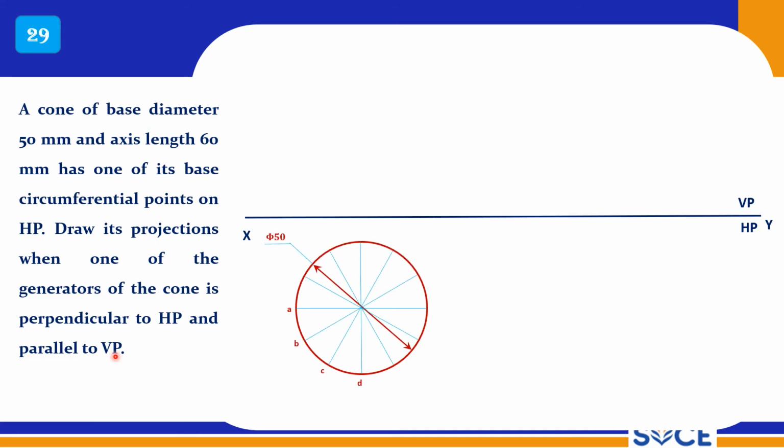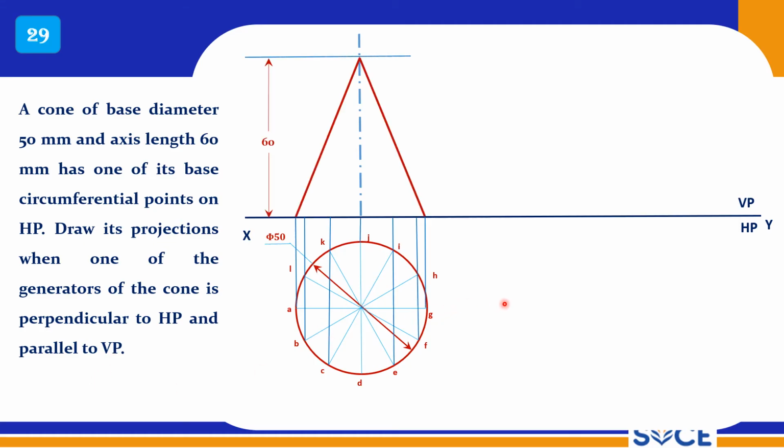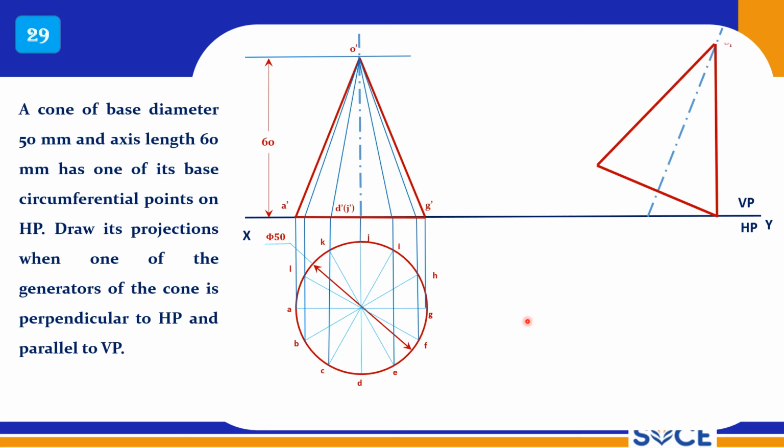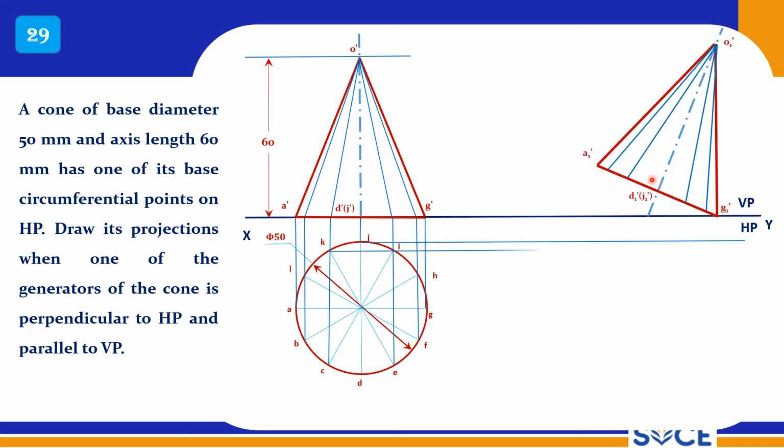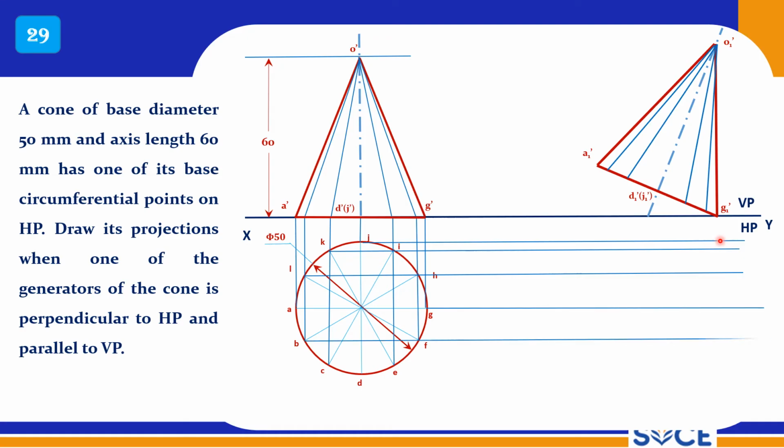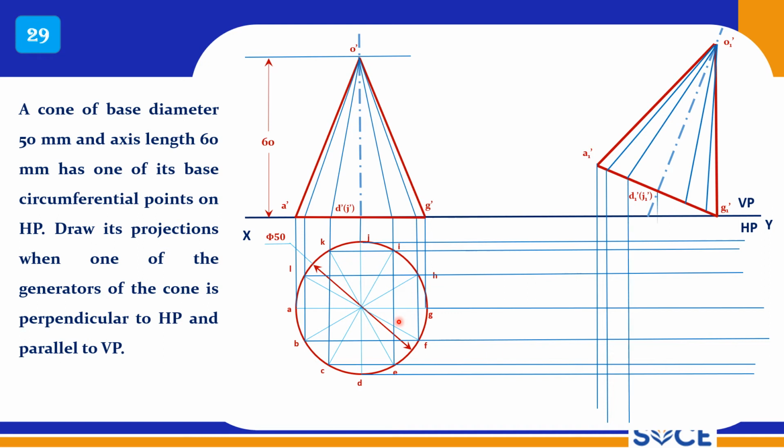So these are the cone points. Divide this into 12 equal parts, and this is my OG. I am going to take OG as vertical to HP, right? Vertical to HP, and OG is vertical. Now reproduce this view here, and the corresponding points you mark here, and draw the projectors from the simple top view and tilted front view, and get the remaining points here. So this is very simple.